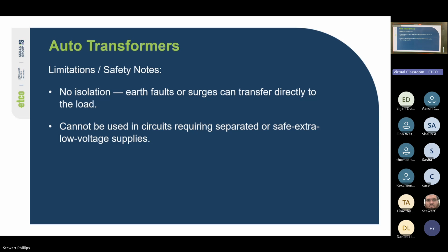Yeah, we could get full line voltage on the output. Earth fault, yeah. It's also known for shock. So you could get things like touch voltages where the voltage rises to a point, especially if it leaks to earth.